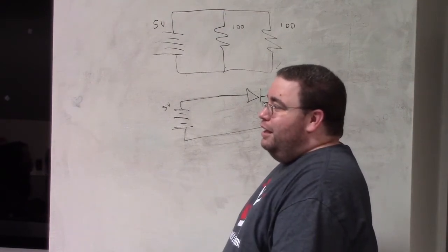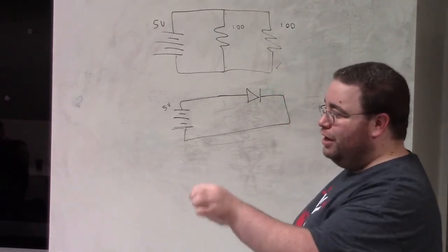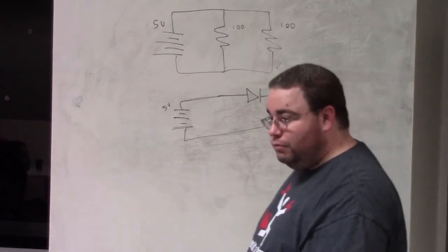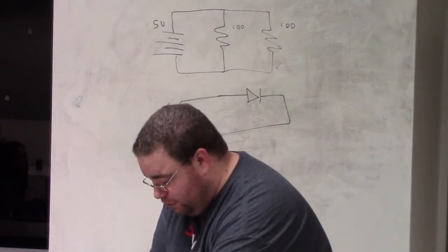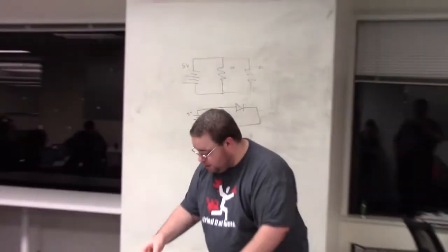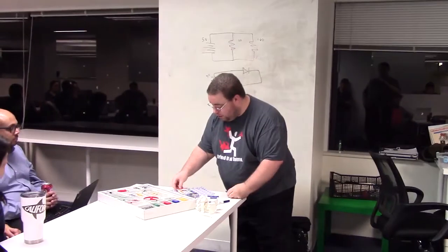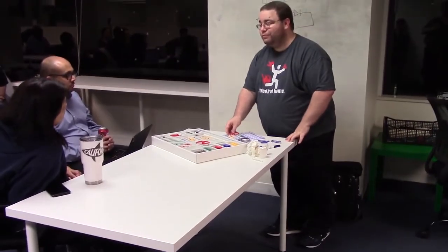If it's slightly wrong, it will go. Yeah, basically, if you twitch the knob wrong. But you can run those in parallel like that, sure, just like you did with the regular bulbs, right? Now what you can't do, and this is kind of interesting, is share one resistor between 2 parallel LEDs.